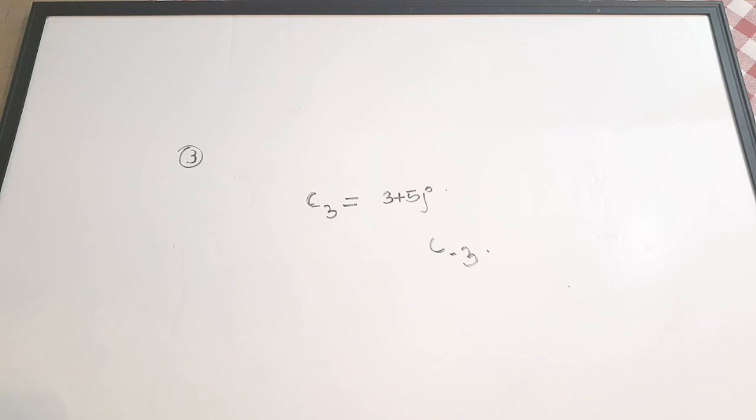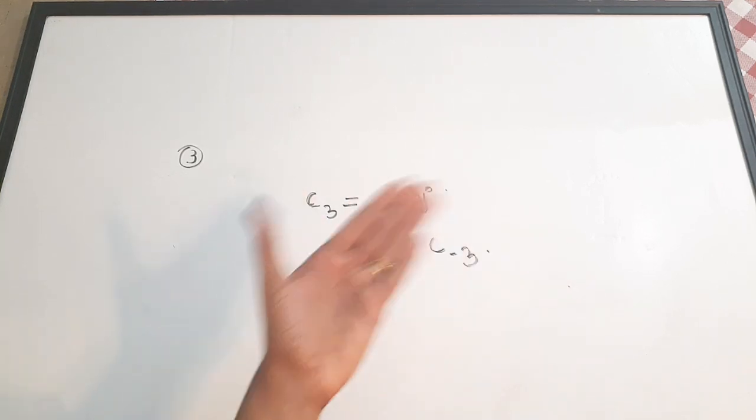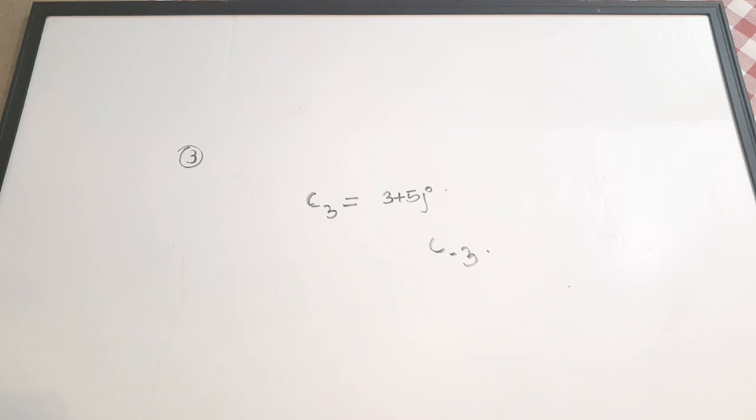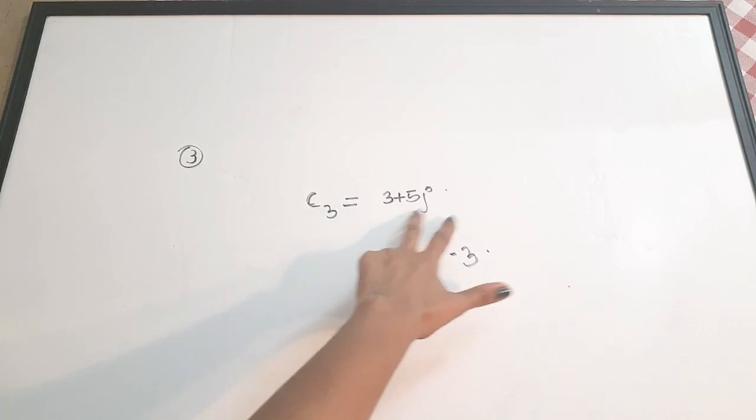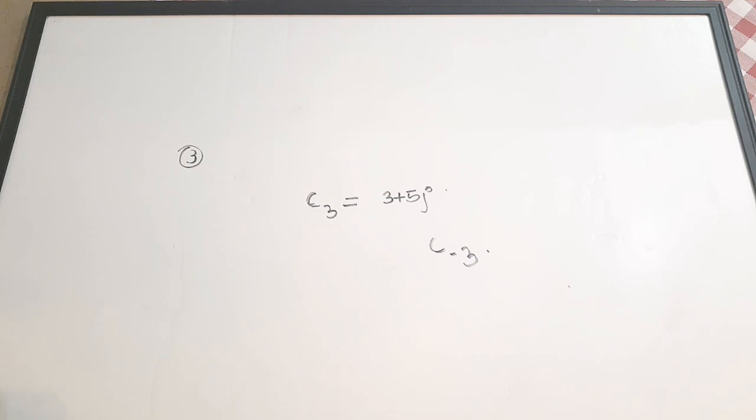So you have been given the fundamental frequency equation. In that the magnitude term is C. Okay, so the various frequency coefficients or the Fourier coefficients are C3, C minus 3, likewise it will go for a Fourier series expansion. These are the coefficients for various Fourier terms. Now C3 is given as 3 plus 5j. Now what is C of minus 3? So how to answer this question is by reading the question once again. The Fourier series expansion of a real periodic signal. So there is the clue. The signal is real and the real signal is periodic.